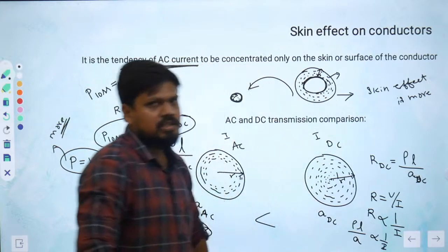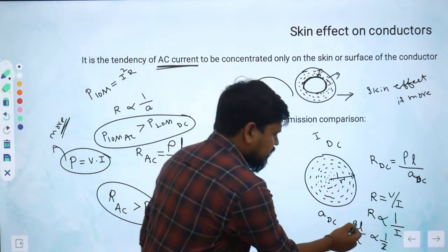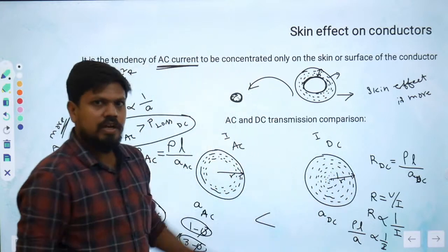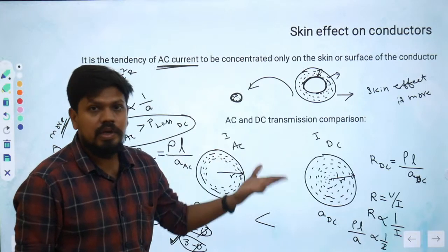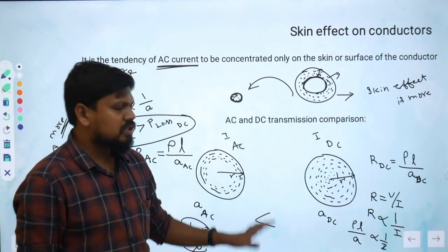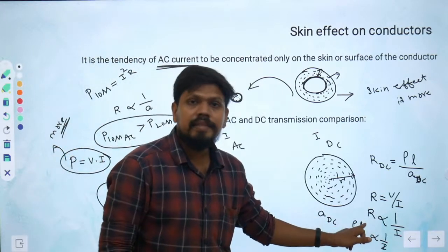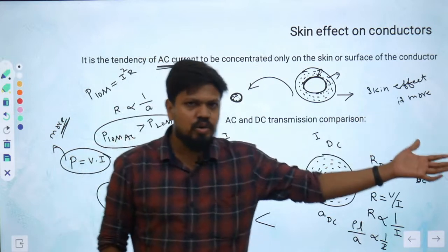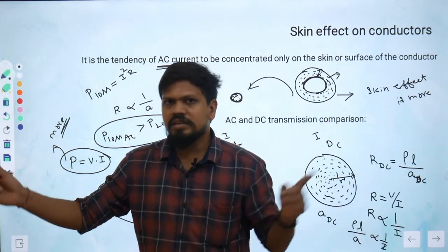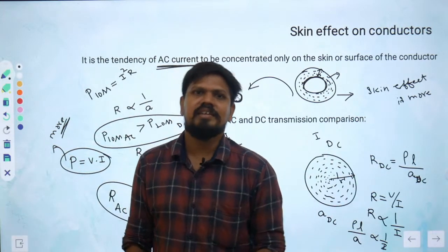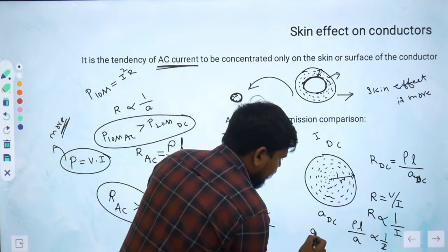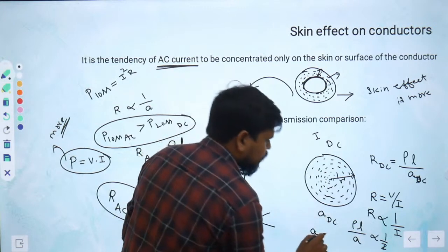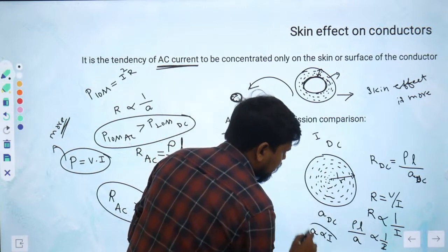During the design stage only this is decided. The resistivity of the conductor is the same. We are using aluminum conductors, so we are not preferring any other material, so resistivity is the same. Similarly, the length of the conductor between the load center and generating center will not be changing, so length is also constant. So the area of cross section of the conductor is proportional to the current flow in it.